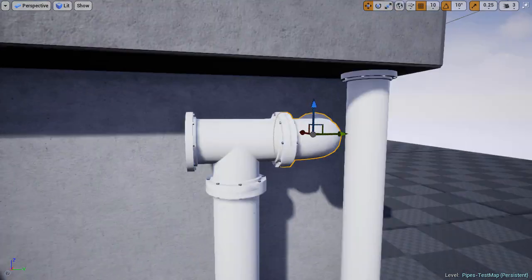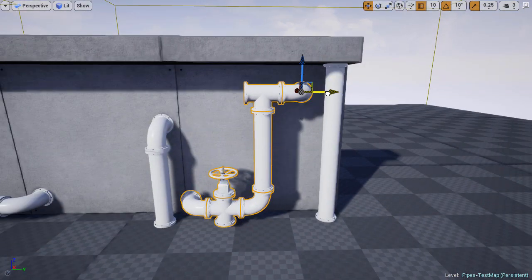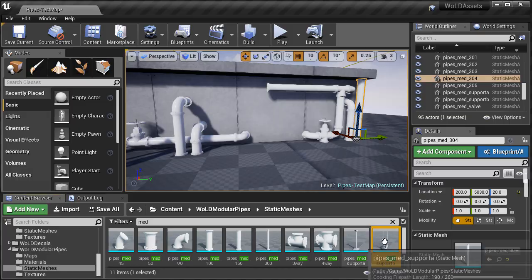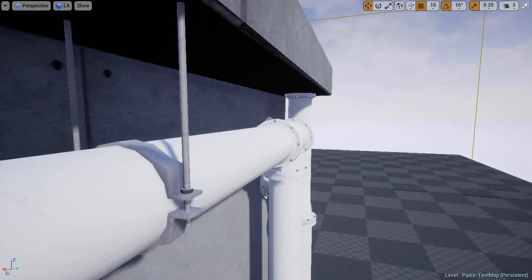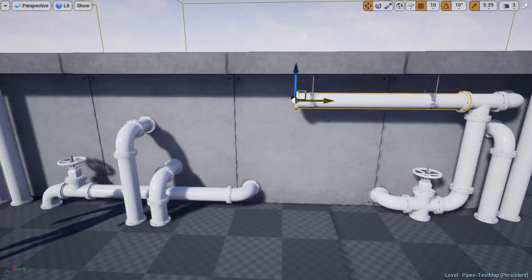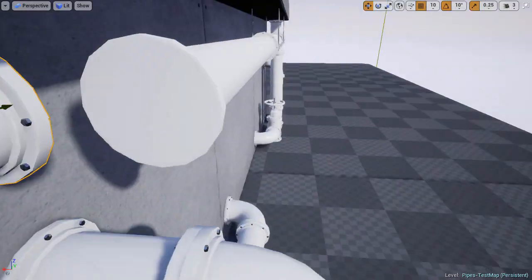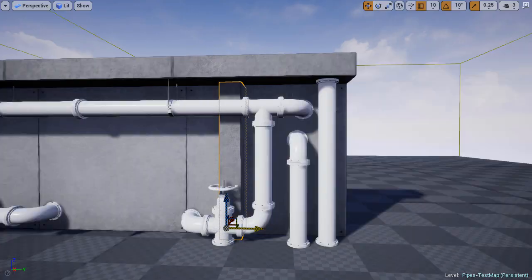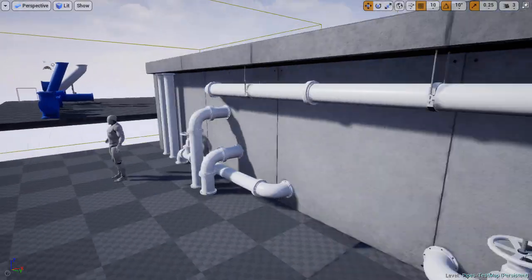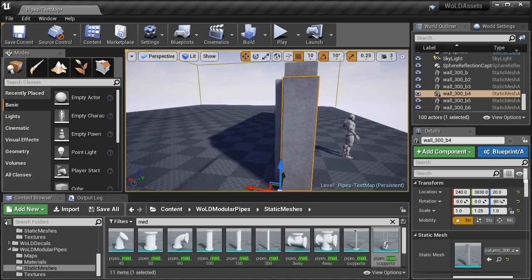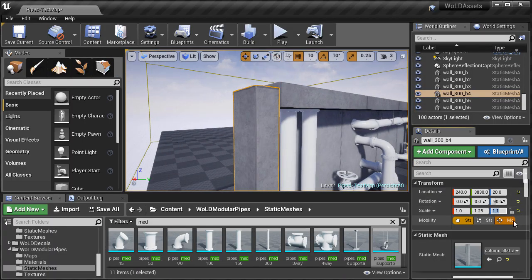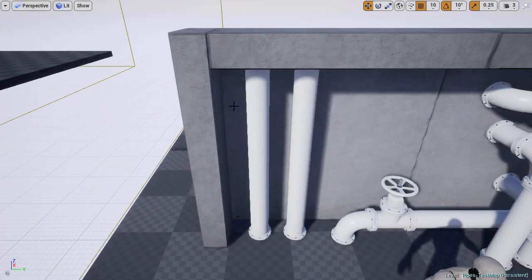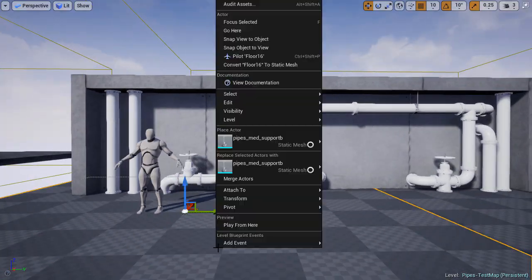And if the default pipe texture color was anything other than white or lighter gray, when I change the color through the material instance, the results are not going to be accurate, because whatever color you are choosing inside the material instance is being blended or multiplied against the default color of the pipes. So after some testing, I had to use a neutral lighter gray closer to white to make the results of color instance change more consistent and more accurate. And a little later, I'm going to change the colors of the medium pipes to orange, and you'll see what I mean.